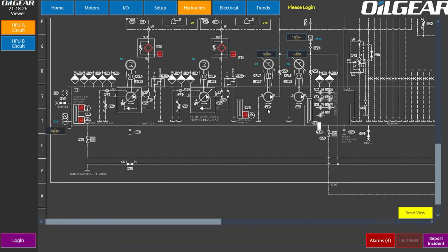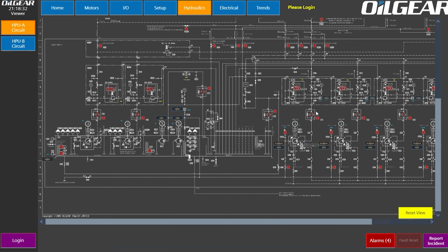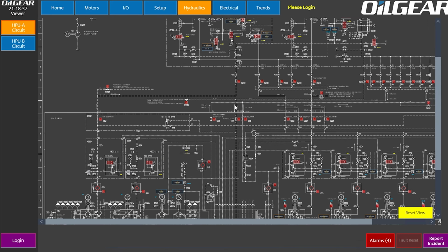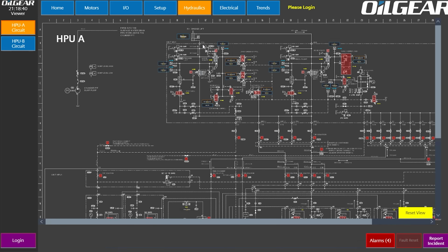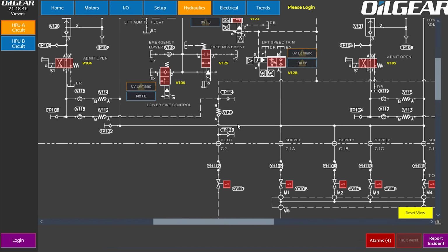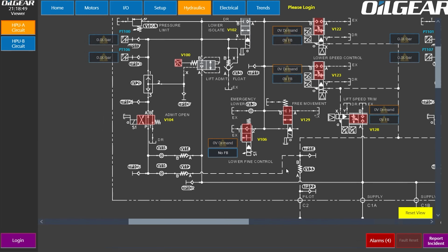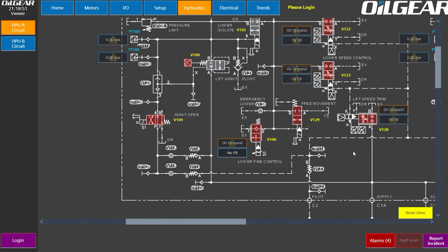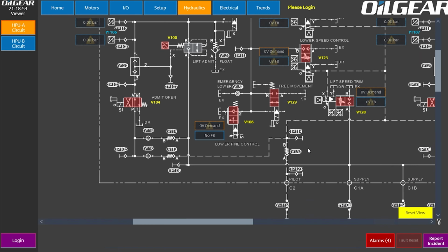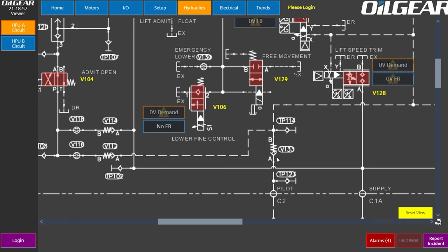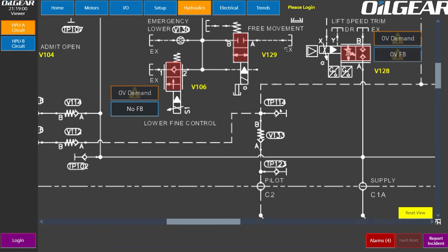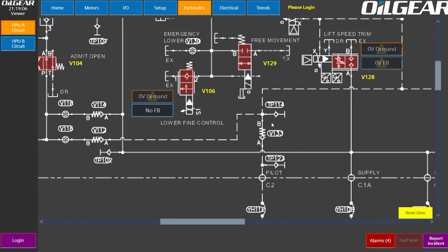Generally, what we want on our HMIs is to be able to display the status of all of these devices. What ends up happening is there's a decent debate as to how extensive a mimic screen should be. Should it show every little thing on the hydraulic circuit, or should it be more of a block diagram? And where are all those gray areas in between? If you don't know hydraulics, it doesn't really matter, but if you have a check valve or a test point there, do you want to display that or not? I'll show you some examples of other hydraulic mimic screens.